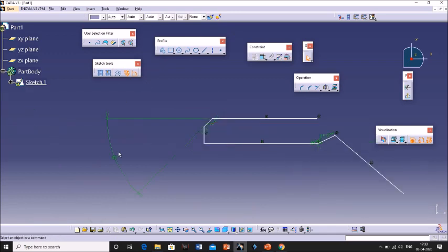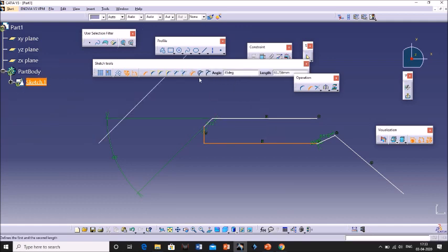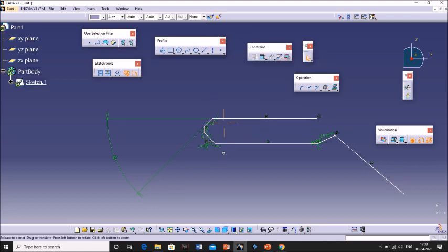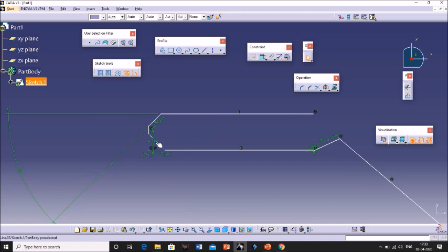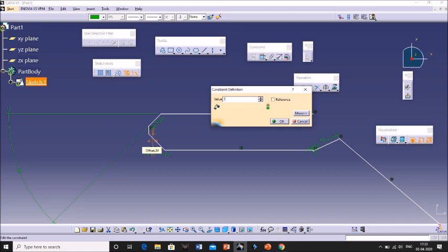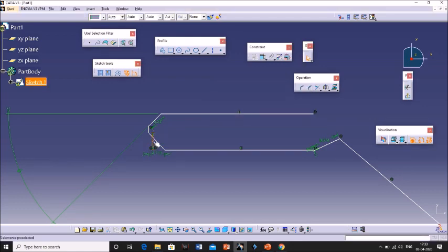inclined line distance and angle, whereas if we select the second option, we get the horizontal distance and vertical distance, that is, first length and second length. So this is the first length and second length. Here the two lengths are equal. If you want to change, just double click on it and change the value. So like this we can change the first length and second length. And here also we can change the angle and the incline distance.